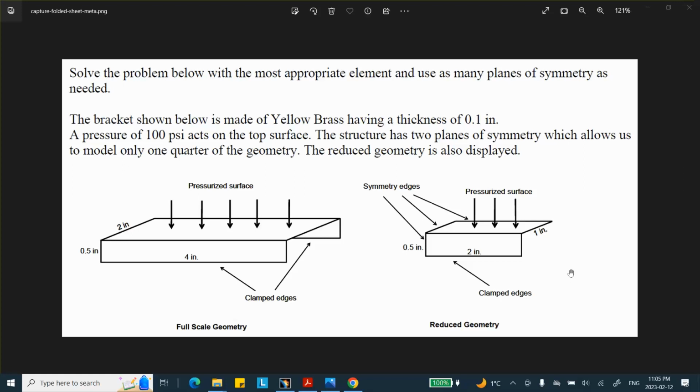Now, the other thing is that in this particular activity, I'm going to create a box with the size that you see here on the right hand side, namely 2" by half an inch high and 1" width. I'm going to make a box and then extract the top face and the side face from it. Now, in the other activities, I generate the same surface different ways. For example, I can draw an L and extrude it directly as a surface without the surface extraction. But I start with extracting the top surface and the side surface, okay?